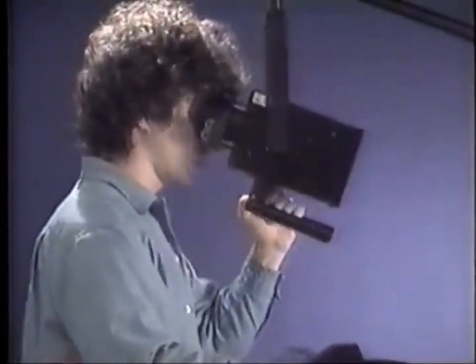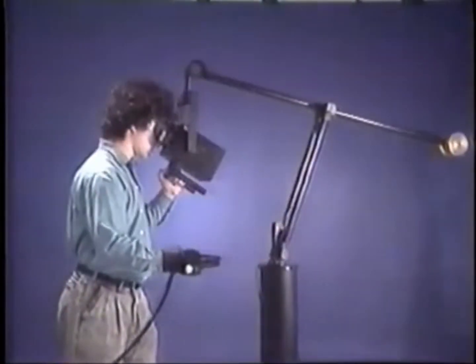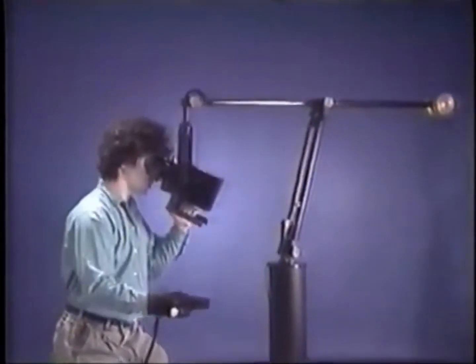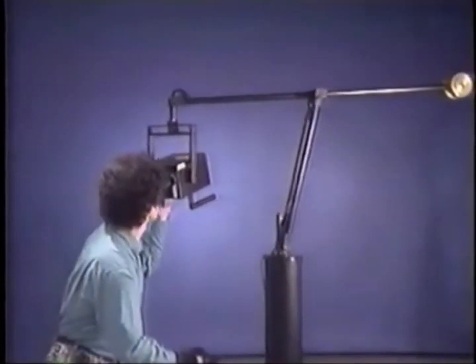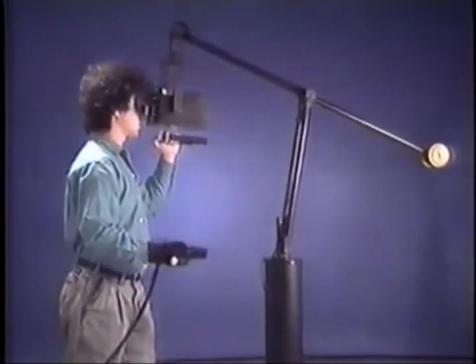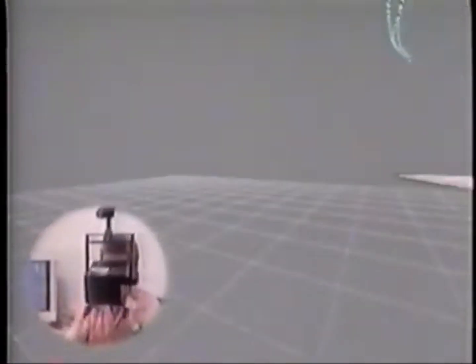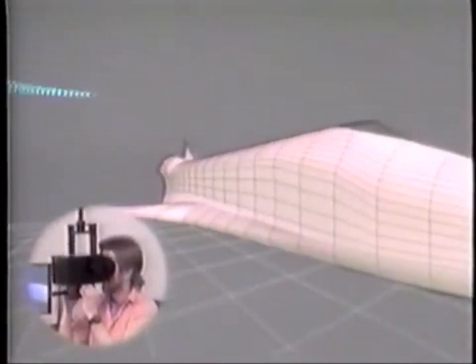To provide the illusion of being surrounded by flow, a unique head-tracking display system is used. A pair of video CRT monitors are used to present high-resolution, wide-field images in binocular stereo to the virtual wind tunnel user. The weight of the monitors is borne by a gimbaled, counterweighted, 6 degree of freedom motion platform known as the boom. Optical encoders at each of the 6 joints of the boom provide high-speed, high-precision information about the position and orientation of the user's head. A high-end graphics workstation renders the virtual wind tunnel imagery in real time, in stereo, from the user's point of view.